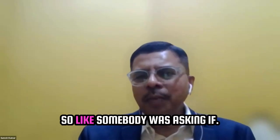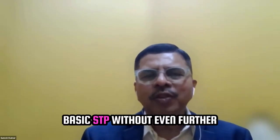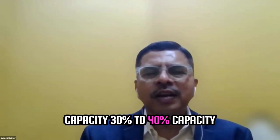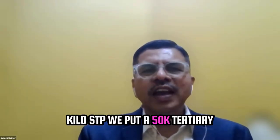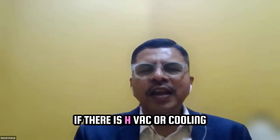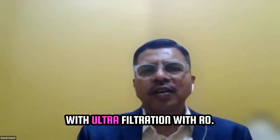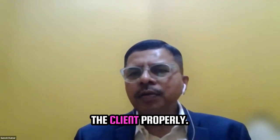Like somebody was asking, if you are going to use it only for gardening, we recommend a very basic STP without even further tertiary treatment. If you want to use it for flushing, we suggest a small capacity, 30% to 40% capacity flushing unit. That means if there is a 150 KL STP, we put a 50 KL advanced tertiary treatment to take care of your flushing requirement. If there is HVAC or cooling tower requirement, what is the requirement there, volume wise? What is the quality required? So how can we achieve that quality? With ultrafiltration, with RO. With these things in mind, we go reverse and guide the client properly.